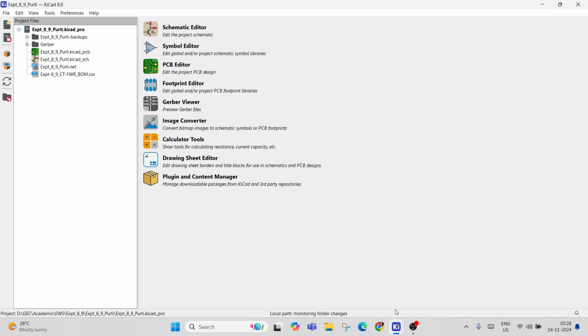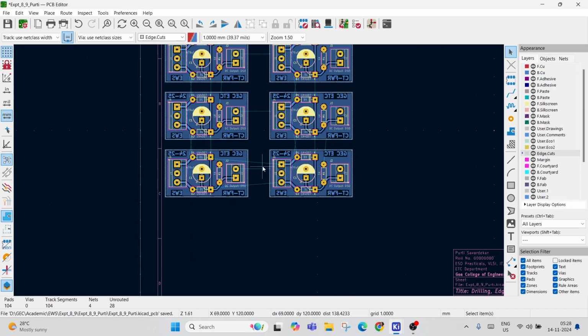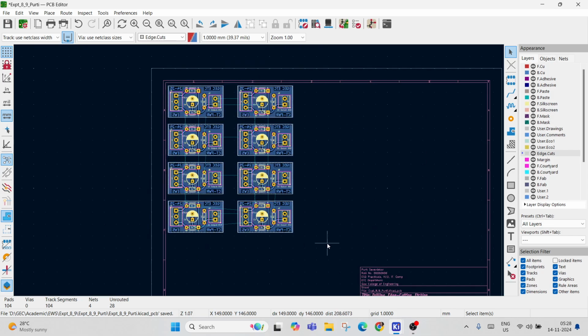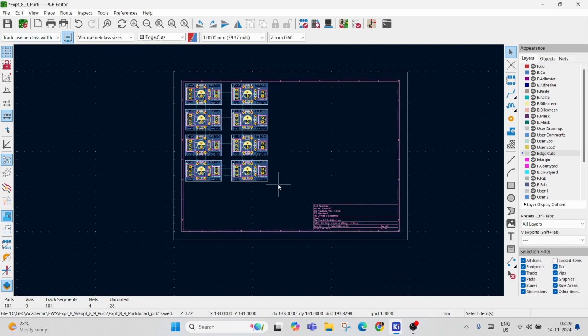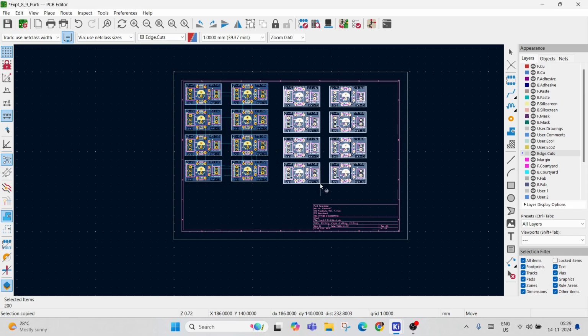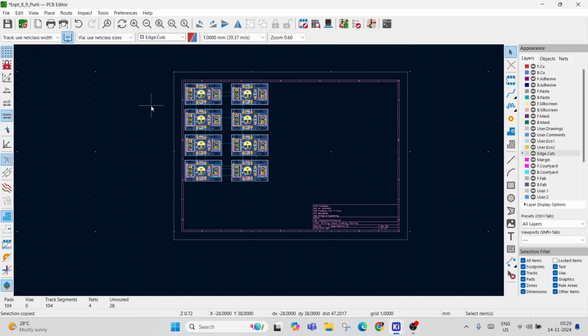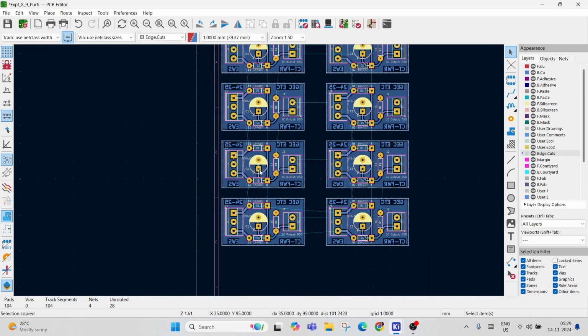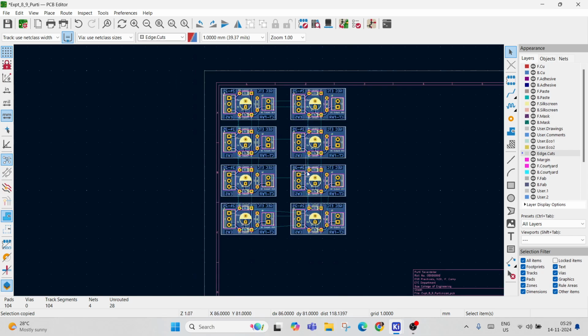Okay, we will go back to the PCB layout. So the plot file is done. Now what I was saying is I will need to do this again because we have made a mistake while printing the PDF. But wait, I will complete the task of generating the drill file first, because the drill file and the edge cut file have to correspond physically absolutely accurately, otherwise misalignment will happen. So I will first try to create the drill file for this.